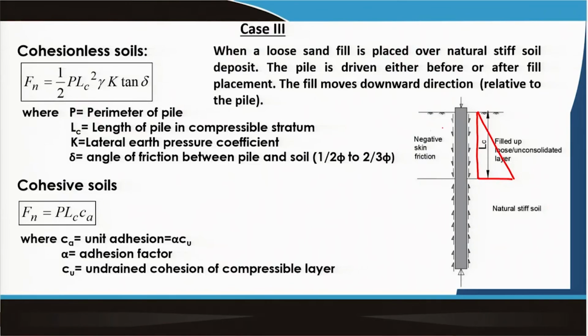But if there is a water table, as I mentioned, then you have to modify this equation or this diagram. That we can do. But sometimes, if the clay soil is placed and the undrained properties are given, in a few cases you will find that even for the first case you should use the drained properties, because that is the actual condition, but sometimes you will find that you have the undrained properties.